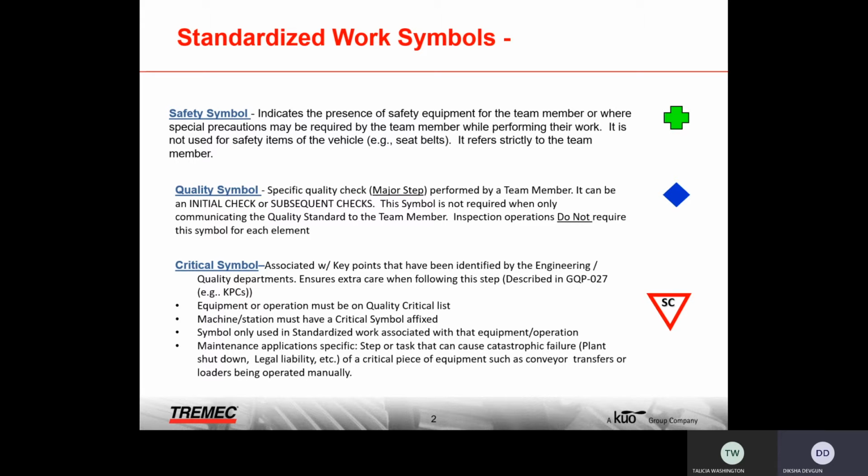Do not mishandle the parts because these are really, really important parts, and they're mainly aluminum, so they can get scratches, they can be damaged. If you do end up dropping a part on the floor, just scrap it. We do not want to use dirty parts and damaged parts in our transmission, especially parts related to the parking feature of a transmission.